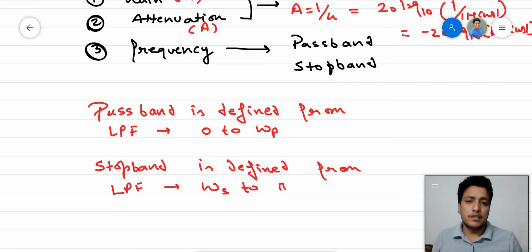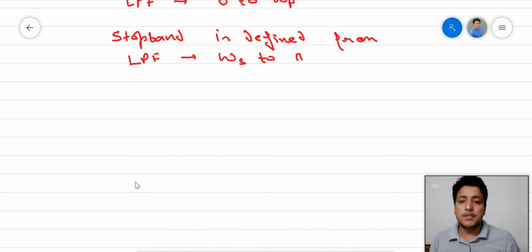whereas the same discussion and most of the terms will remain the same for band pass filter or high pass filter. Just the frequency domain which we are representing right now will be different, or the characteristic curve will be slightly shifted towards the respective frequencies when we discuss those particular filters. Otherwise everything in terms of attenuation, gain, frequency response or transition region will remain the same for all the cases, just their location will vary on the frequency axis, because discriminated frequency will constitute a band that is called stop band, pass frequency will constitute a band that is called pass band. There are few points for the filter specifications, just like gain and pass band, we want to discuss right now.